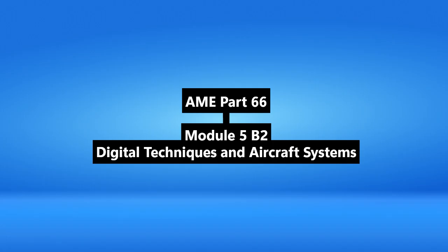Okay, one-way street. And then the module mentions ARINC 629, specifically on the Boeing 777. Sounds like a bigger deal. It is, yeah. A significant step up. Much faster data rate, 2 megabits per second, and it can handle way more terminals, up to 131. The big difference from 1553 is there's no central bus controller. Ah, okay. How does that work then?